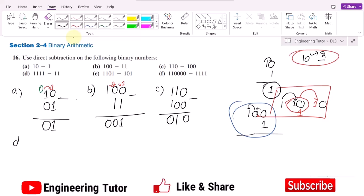Similarly, part D of my question, this is basically a 4-bit number, and similarly here I have this 2-bit number, and I have previously told you that whenever I have the lower number of bits here, what you have to do in the MSB, you have to write these zeros. Okay, so now in order to subtract them, 1 will be subtracted from 1, this will give me 0, this will also give me 0. Okay, this will be 1 and this will be 1 as well.